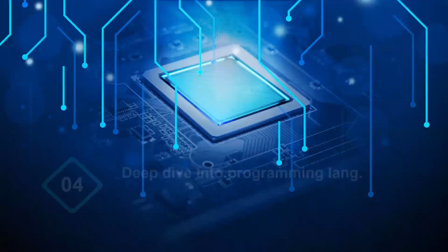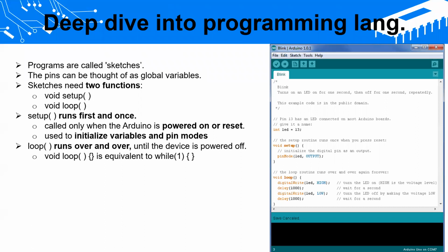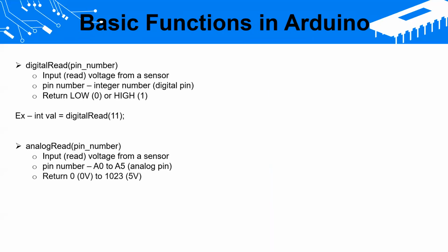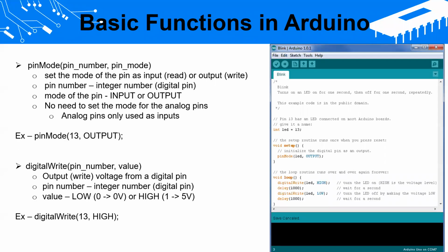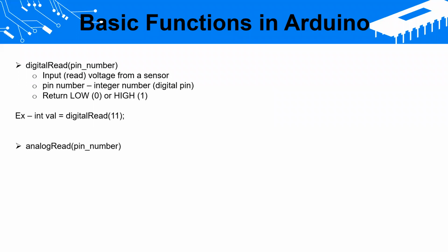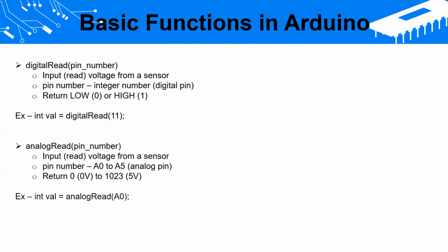Then yeah, we discussed digital write. Then we were at analog read, right? So the maximum value, if you're using analog reads, right? If it is analog, then it is a read, then you should use the analog pins A0 to A5, right? So this value will be between 0 and 1023, right?